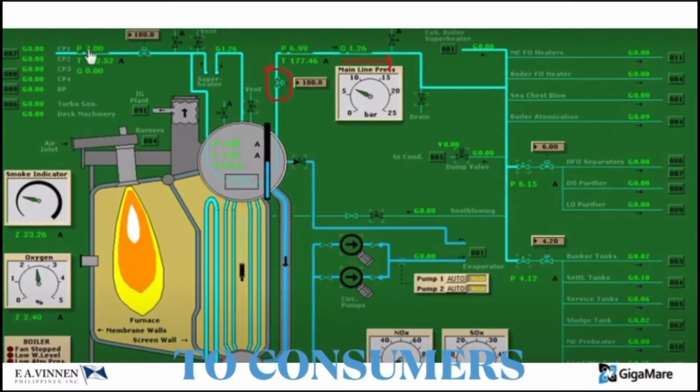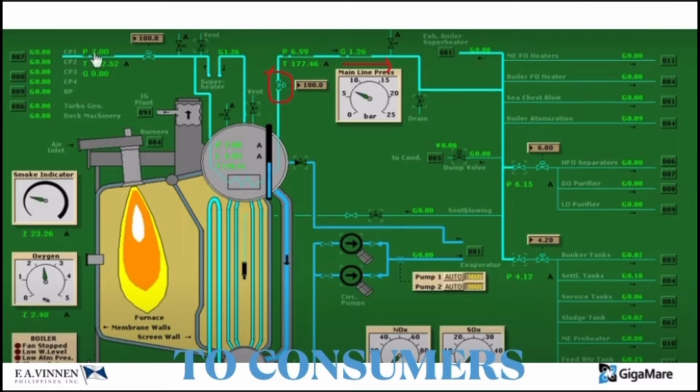Once the boiler has reached the desired pressure and temperature, it is now time to open the main steam valve in order to supply steam to various heating services, such as the heaters in the purifier, the main preheater in the main engine, and also the engines, the fuel oil tanks, service tanks, storage tanks, and so on and so forth.